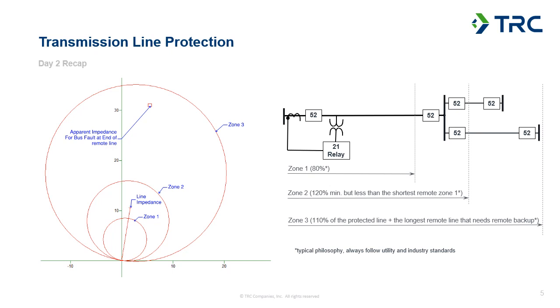We'll allow those to operate their breakers and clear the fault on those parts of the system before we trip off this line that otherwise doesn't have a fault on it. So we want to minimize that system impact and maintain the selectivity of the system.